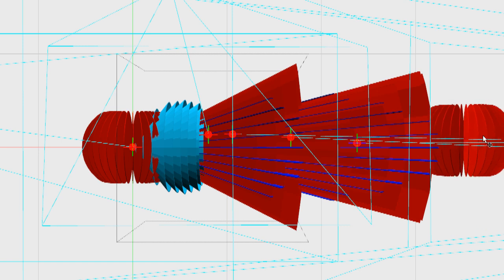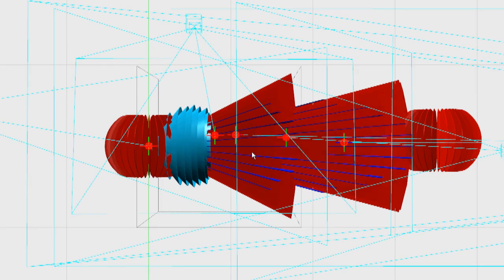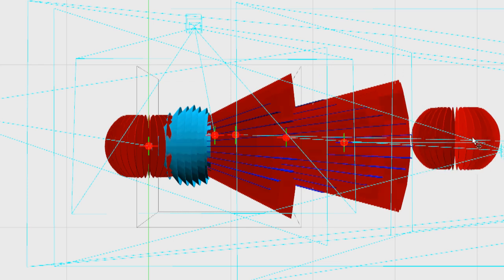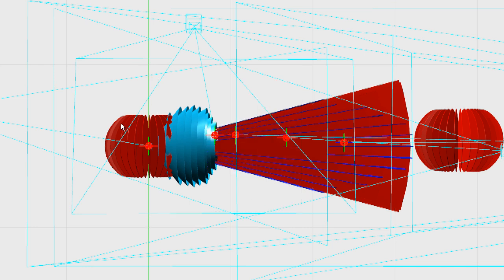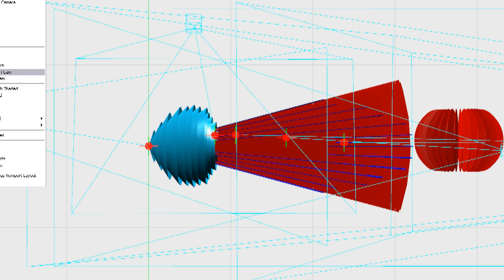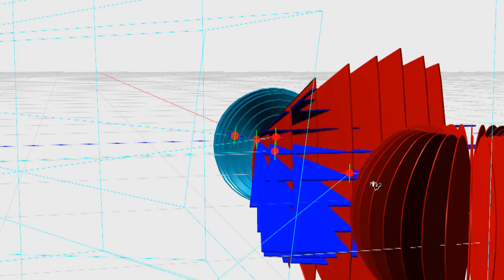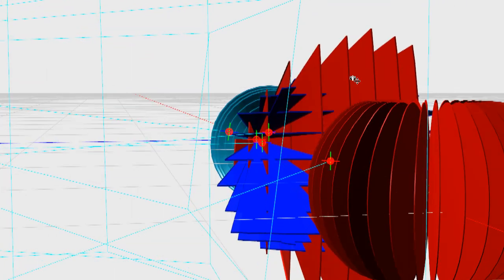One of the recommended setups, if money was no object, would be to have two diversity systems, in which case you could have the best of all worlds. Personally, my plan would be, let's turn everything off, you'd have a diversity receiver connected to two Yagis, one horizontal and one vertical.